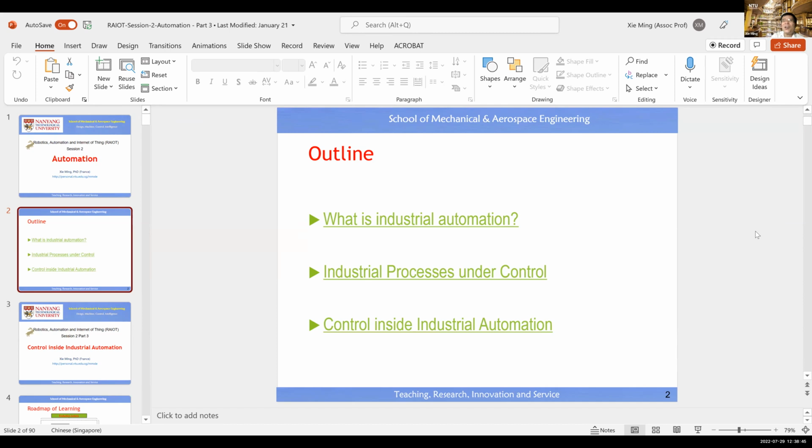The additional knowledge is that the design methods in control theory make use of equations in the frequency domain, because equations in the frequency domain are much simpler than equations in the time domain. That explains why control theory uses the Laplace transform, because a lot of students have trouble understanding why Laplace transform.